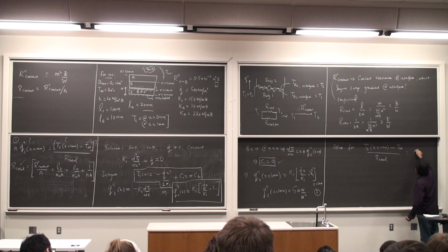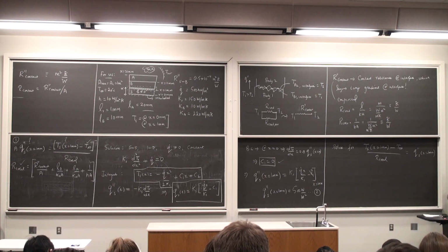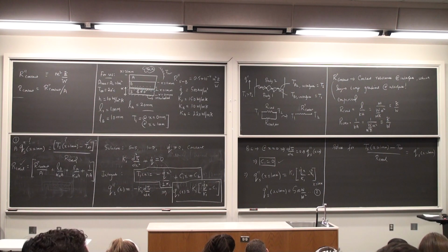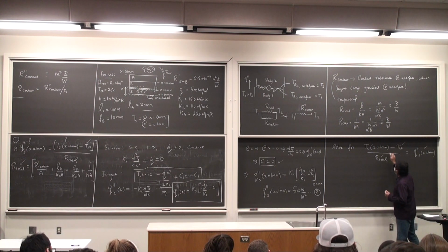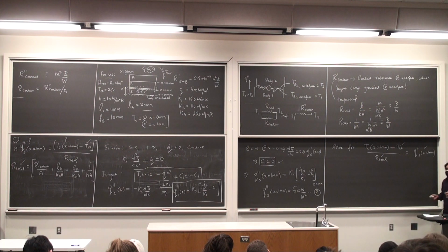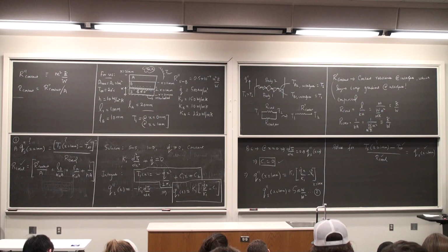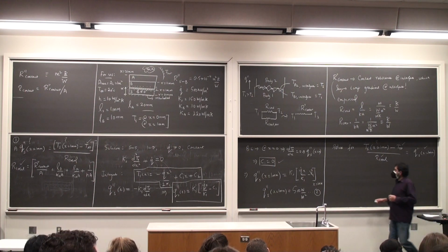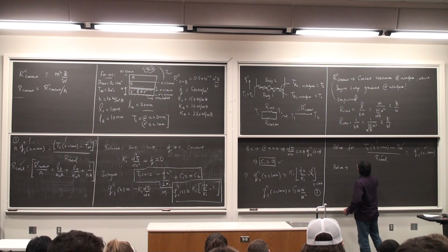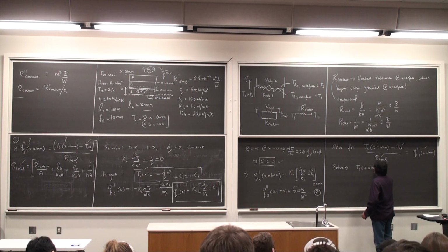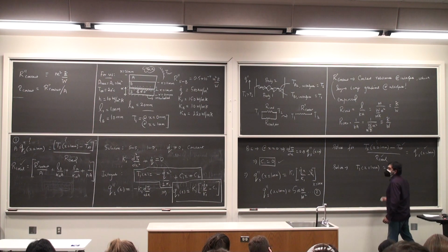This is equal to, okay, all of these are known except for the temperature. At x is equal to 1 millimeter, everything else is known to me. So this is known, the T infinity is known, R total is known, all the parameters of the problem are given to me. This is the only unknown for me. So, to solve for Ts at x equal to 1 millimeter, it is approximately 70 degrees Celsius.